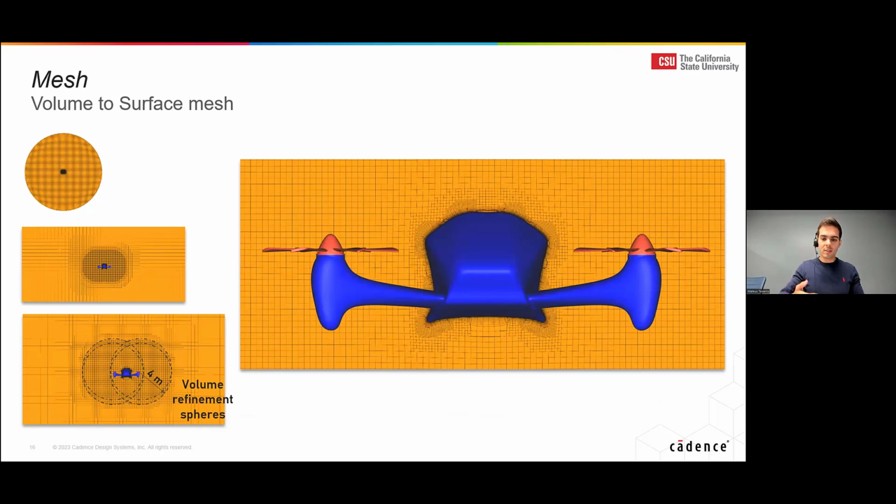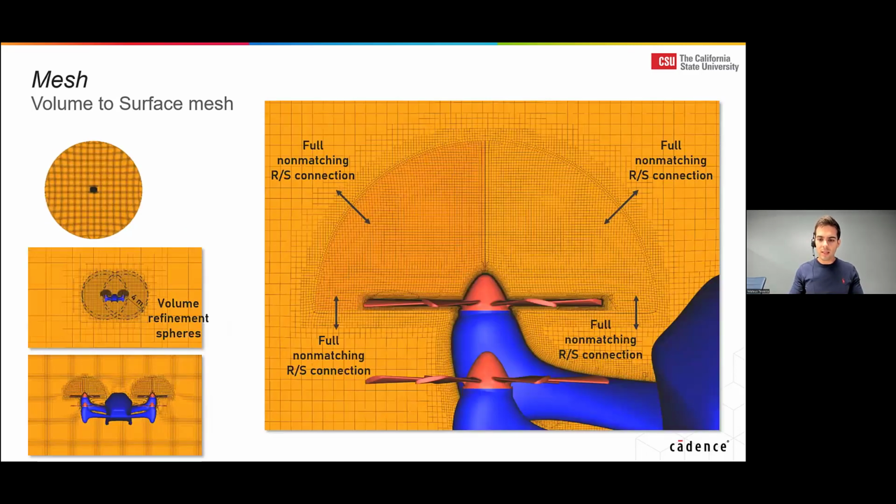So just for you to understand, I'm not doing a surface mesh, it's actually a volume mesh, and this is a cut through the sphere, and you can see here every little square representing one control volume for which we're going to try to converge the Navier-Stokes equations that are used in the formulation of the method for the computational fluid dynamics simulation. Now, I mentioned before that we did 2 types of domains, rotating domain and stationary domain.